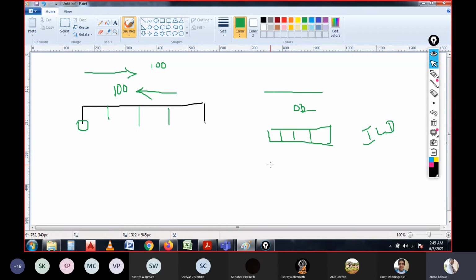But in the truss, we need to consider only the forces, compression as well as tension, since we won't get any shear force and bending moments in the truss. I hope you know that in a pin jointed truss, there will not be any shear forces and bending moments because the loads act on the joint itself. So for that reason, we need to calculate the particular stresses.